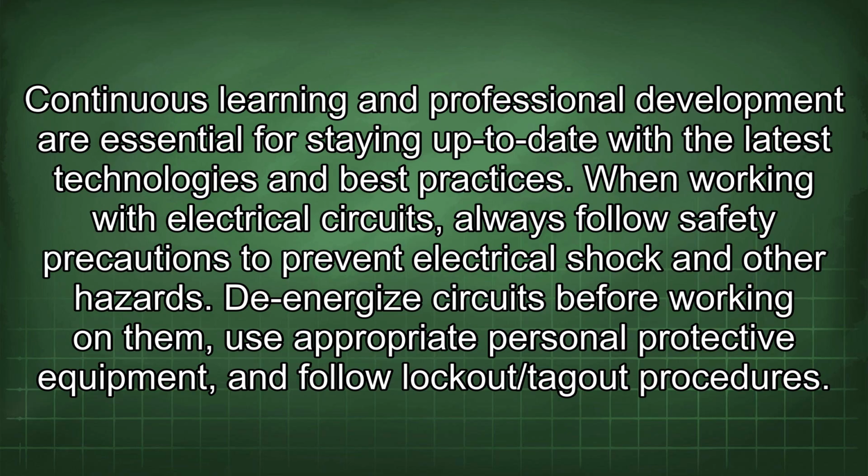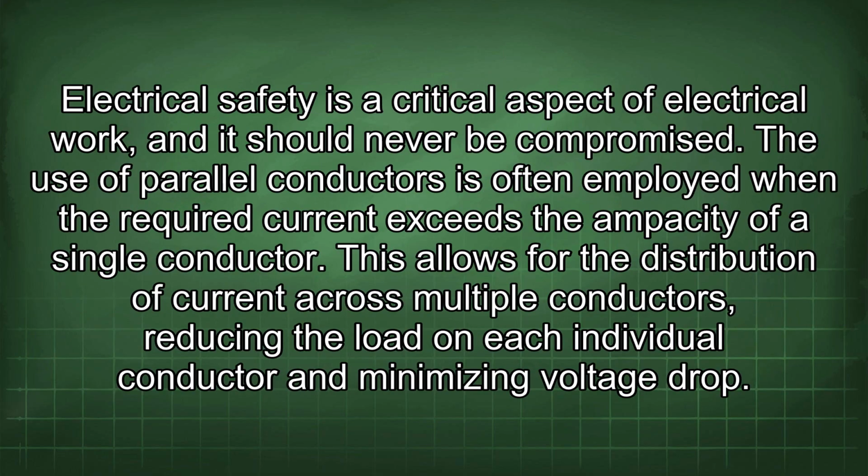When working with electrical circuits, always follow safety precautions to prevent electrical shock and other hazards. To de-energize circuits before working on them, use appropriate personal protective equipment and follow lockout/tagout procedures. Electrical safety is a critical aspect of electrical work, and it should never be compromised.